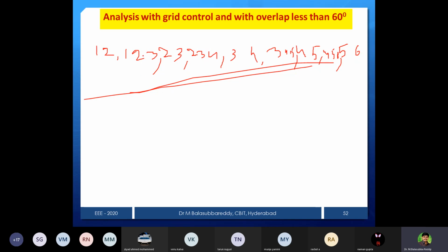So now you can see what I want to do is get the average output voltage. In the previous case, whether 1 2 is conducting or 2 3 or 3 4 is conducting, you get the same duration of pulses. You just integrate and multiply by 6, and you get the average. But now, the total is 60 actually. If this duration is u, whatever, then what is this duration?